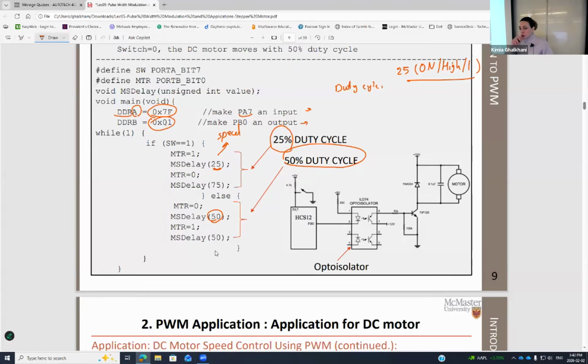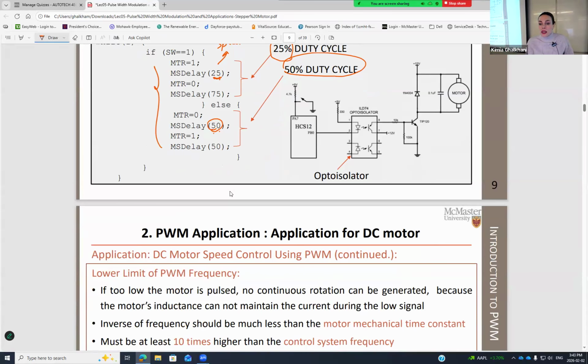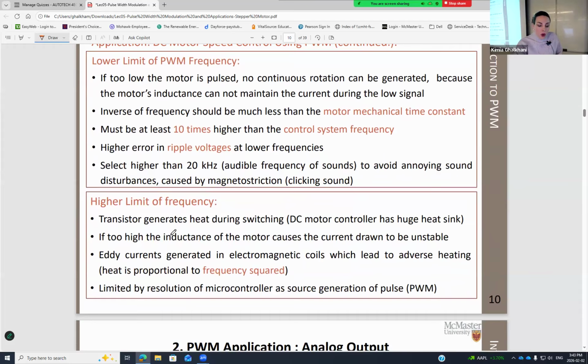Output is connected to the DC motor. I already programmed this template for you, and you are going to see it tomorrow. You are going to just change the duty cycle, and through that duty cycle, you are going to change the speed of rotation. This is going to be the task for tomorrow. I'll get you to connect this part of the circuit inside the lab, but the remaining parts are already set and ready to use. Now let's look at why we do all of this.